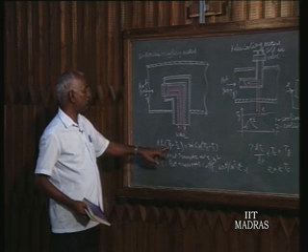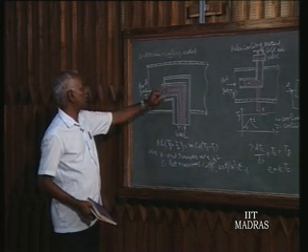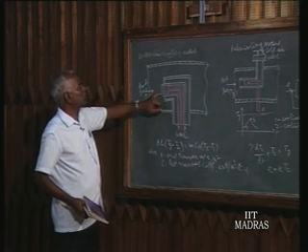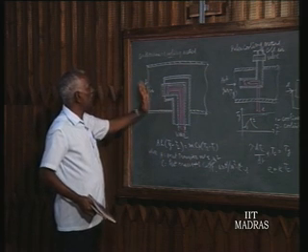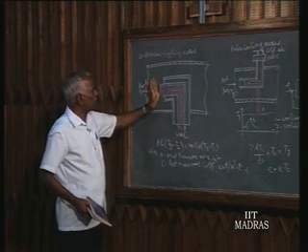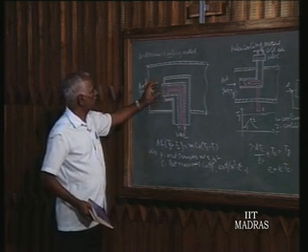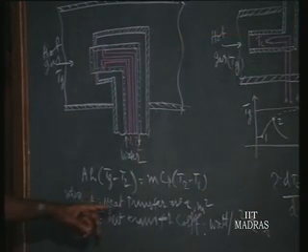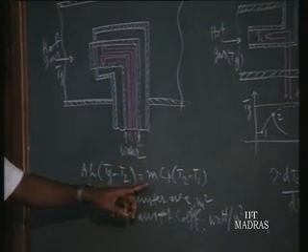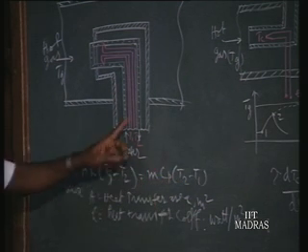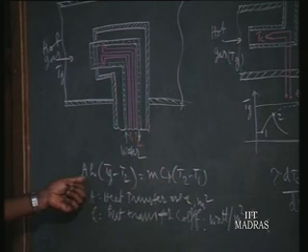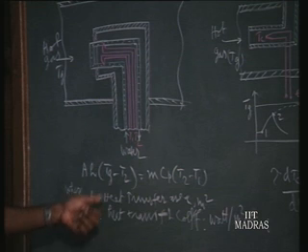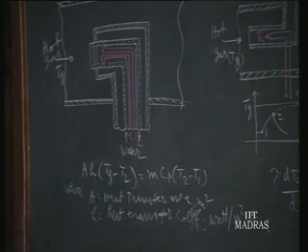And Tg is the gas temperature, T2 is the output temperature of water. So that heat is conducted across the temperature difference of Tg and T2. That heat conduction is equal to the heat gained by the flowing water. They are equated. From this, M is known by measurement, and T1 and T2 are measured by the thermocouple, and A and H and all are constants available. So we know the unknown temperature Tg. This is the continuous cooling method.